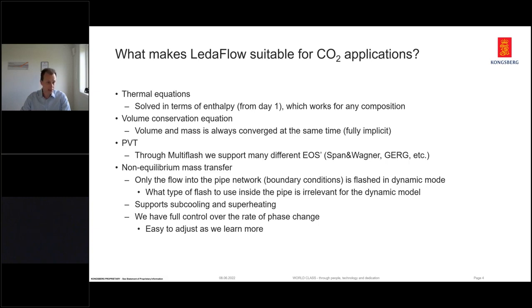And finally, LedaFlow contains what we call the non-equilibrium mass transfer model. So that means that only the flow into the pipe network, so that's the boundary conditions, are flashed in the dynamic model. But basically what that means is that we don't do any flash calculations inside the pipe. And that also means that any discussion on whether to use PT or PH flash calculations is irrelevant for the dynamic model.